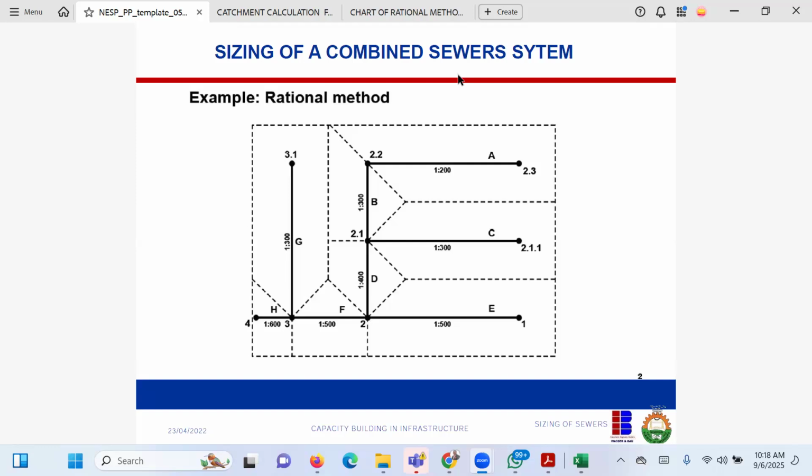Okay, remember what I said last week? Sewers are designed based on garbage in, garbage out: what goes in is what goes out. So you use the drinking water parameters to design your sewer systems. At the end of the day, when they ask what the flow is, it simply means the total population multiplied by the design parameter per capita per day, depending on whether you are using individual population equivalent or land use. Land use simply means how many people you are anticipating per hectare, per area. You now multiply it because it's virgin land.